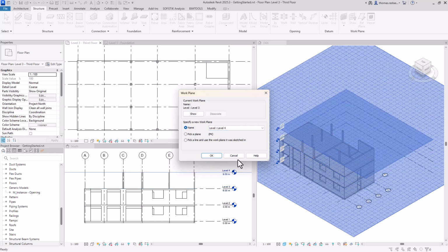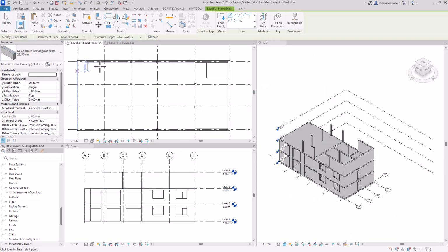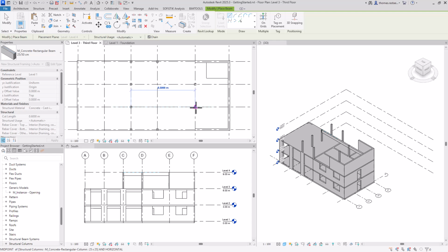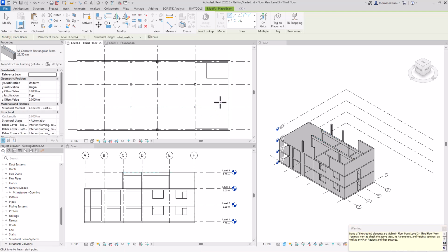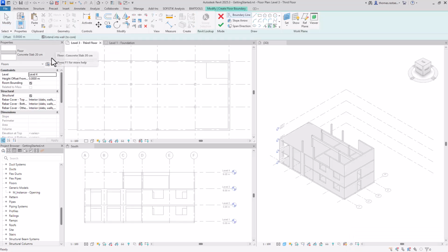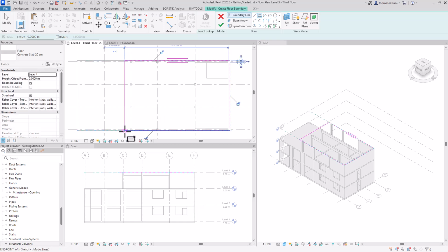We insert the top floor beam on level 4, spanning from columns to the walls. Then we model the level 4 slab with a thickness of 250 millimeters, using temporary dimensions to set its length to 13.75 meters, measured from the exterior face.